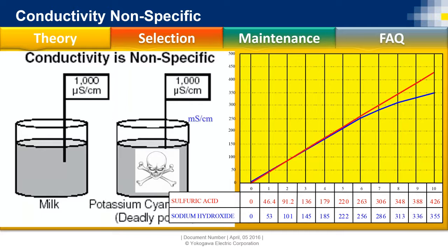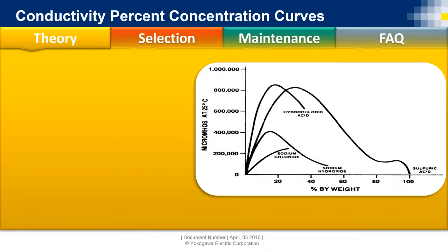So at a certain point, when you're in the lower range, sometimes we may use pH measurement along with conductivity to know, okay, is this 50 millisiemens I'm seeing because of sulfuric acid, or is it because of my base, my alkaline solution? So we just need to know exactly what we're measuring. And we'll show you in just a moment why.